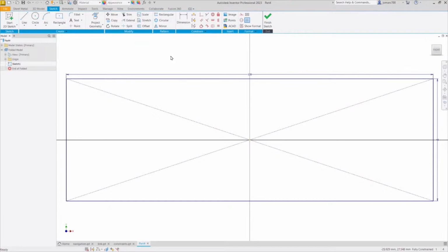Next, let's create two circles. Shortcut key for that is Control Shift and C. Let me create this first circle over here. Next one over here. But this time, notice once more that dimension which is currently highlighted. I'm going to key in 10. Hit enter. Next, this circle and this circle should have an equal value.